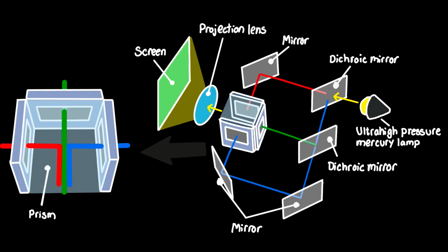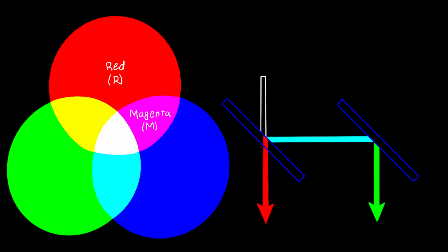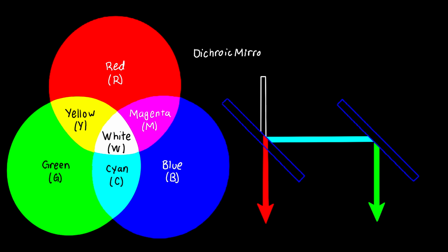With today's technology, LCD projection directly competes with single-chip DLP projectors. They are easily found with brightness of 10K lumens or more, and are relatively cheap compared to DLP projection. Some disadvantages you see are low life due to degradation, and most LCD projectors are non-sealed. Non-sealed is the term used to describe the light path, panels, and cube not being sealed to outside elements. Dust, dirt, and even fog juice can settle and cook on the various pieces that make up the light path of an LCD projector.